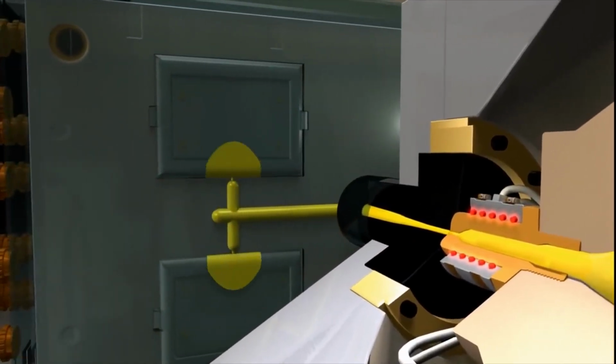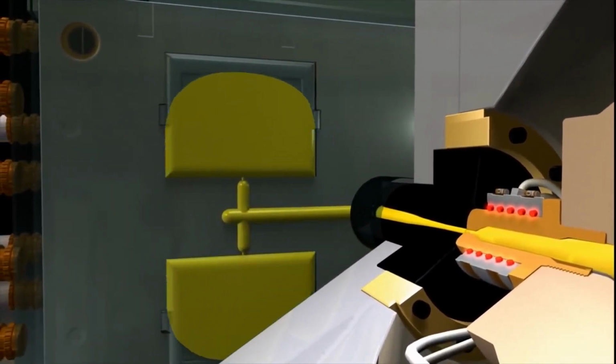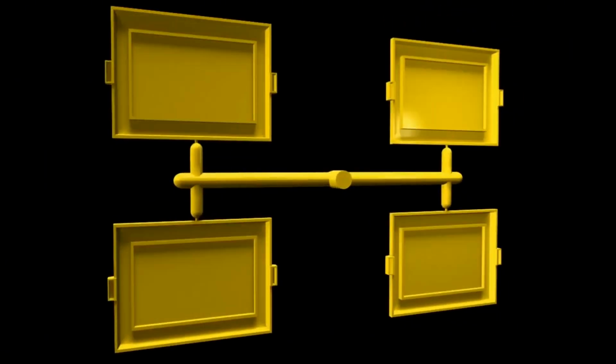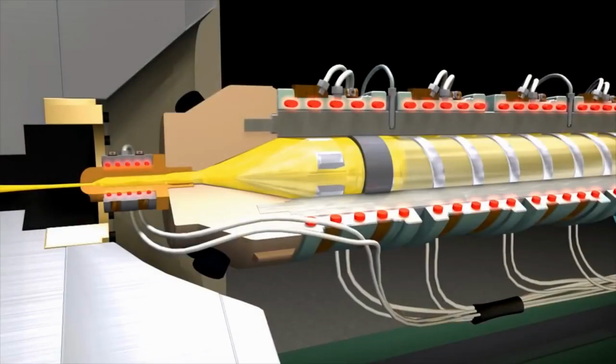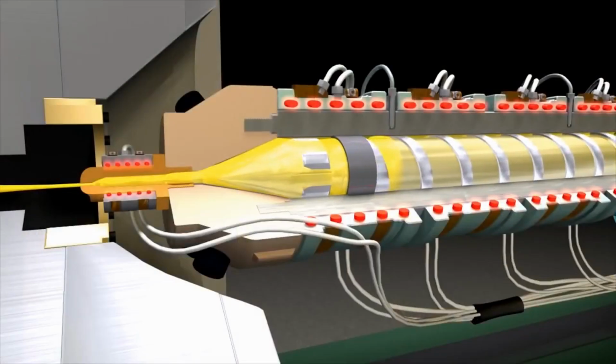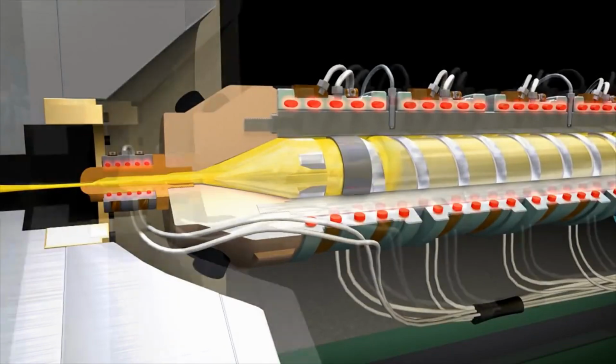Reasonable setting of holding time and cooling time is very important for the quality of transparent products. If the holding time is too short, the product may have problems such as shrinkage and dimensional instability. Too long a holding time will increase the internal stress of the product. With insufficient cooling time, the product may be deformed due to incomplete cooling, affecting the transparency and dimensional accuracy. If the cooling time is too long, it will reduce production efficiency.